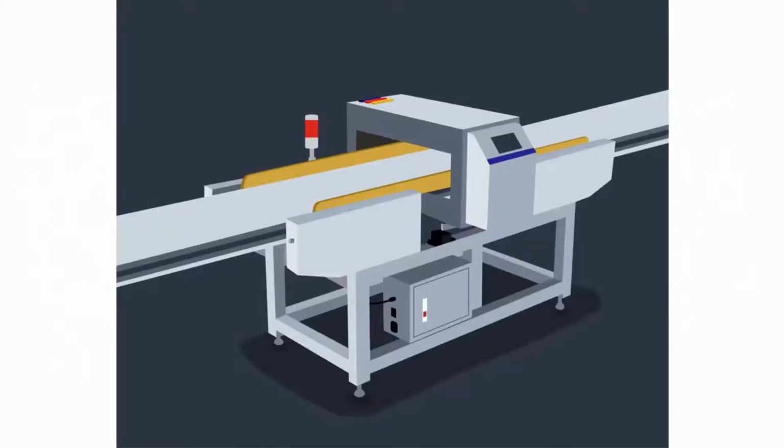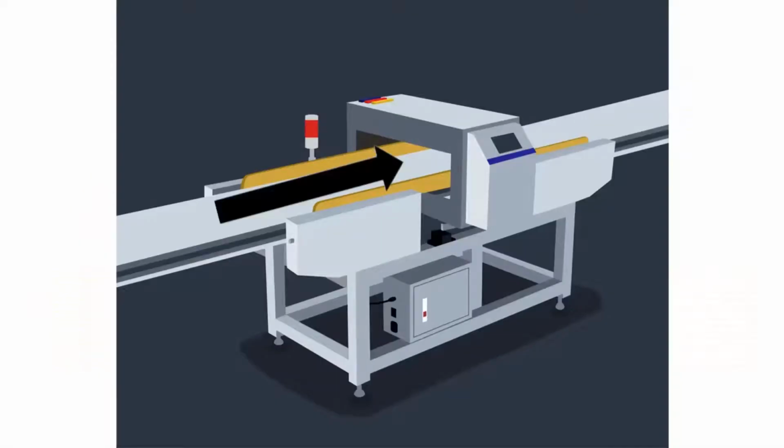Performing monitoring procedures for a metal detector. This is a picture of metal detector test wands or strips used to verify that the metal detector is working properly. They contain small pieces of different metals inside. The test wands should be detected once they pass through the metal detector, when the quality control technician is performing the monitoring procedures.